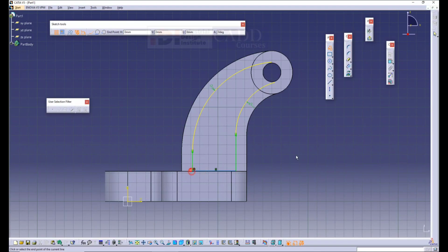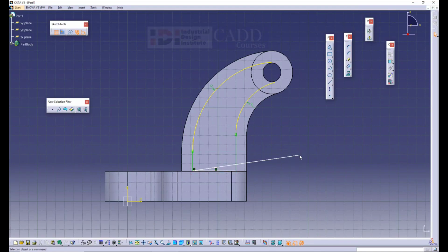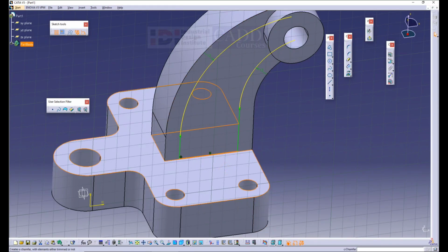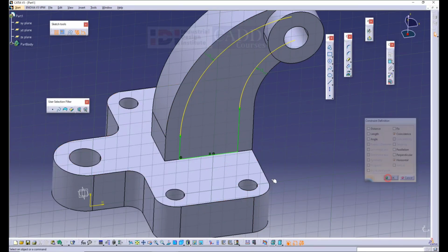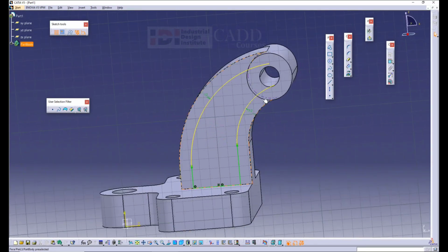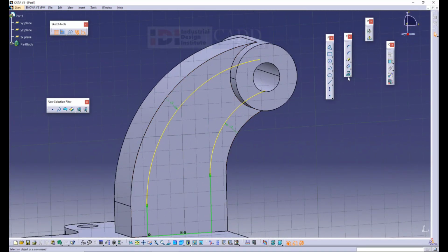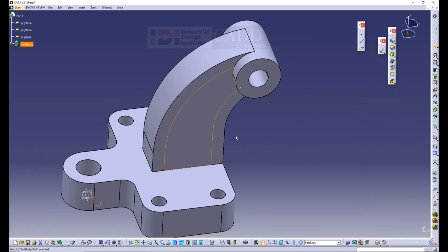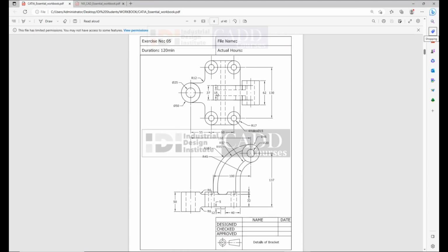Yeah. So I close the component. I close the sketch where I've created, but I have to give a coincidence. So try to make it green in color, which is nothing but completely constrained. I project this corner, and the excess I will delete. Yes, done. Go out.